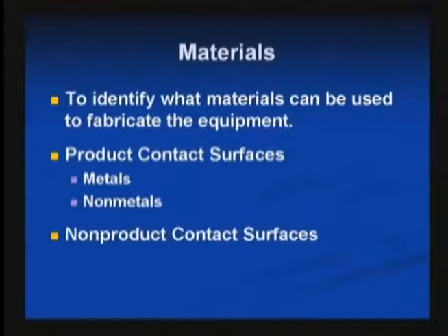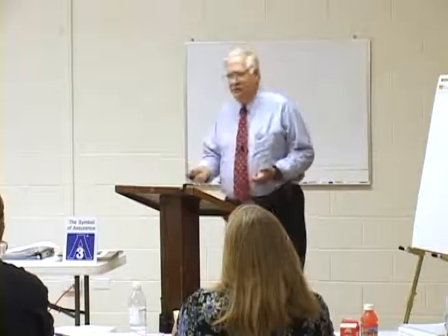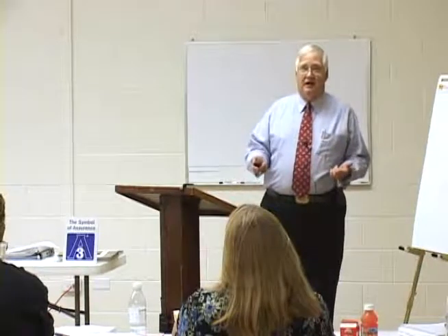Materials also define non-product contact surfaces. We want these surfaces to be cleanable, but they're not quite as critical, obviously, as the product contact. So you might be allowed zinc-coated fittings or even some brass fittings on airlines. We don't want the standards to be so impractical that companies can't use off-the-shelf components for certain parts, as long as they're far enough away from the product contact areas.